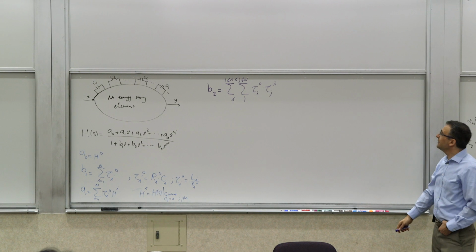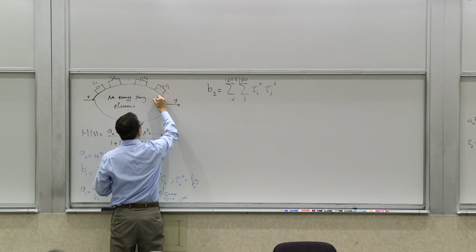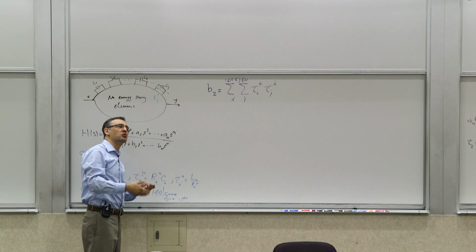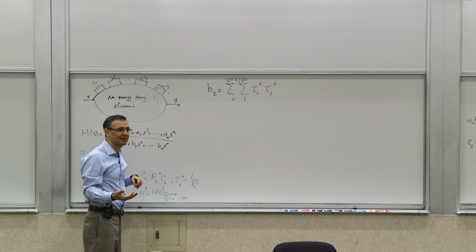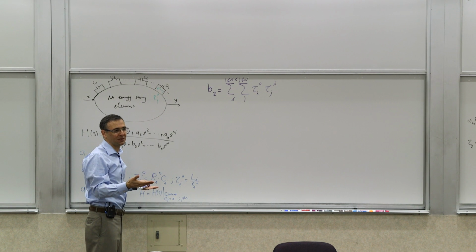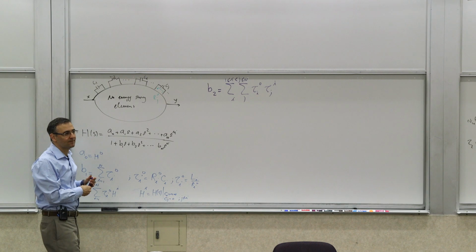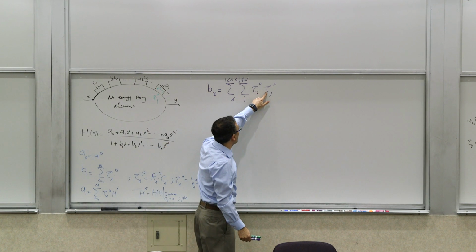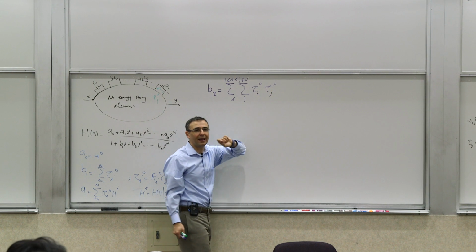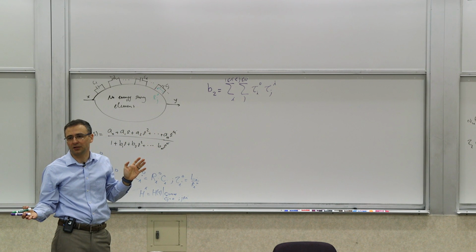No, element j is the element in question. We don't really care; we are caring about the resistance seen by element j. We are looking at Rji. So it's neither infinite valued nor zero. You can think about it as being removed. You're only looking at the resistance seen by it. That's a good question, right? Because if you infinite value it, you've shorted it. You can think about it as being not there, being zero valued. So the subscripts are always associated with the element in question. The superscripts are the indices of elements that are being infinite valued. And that's all you really need to know to understand this notation.